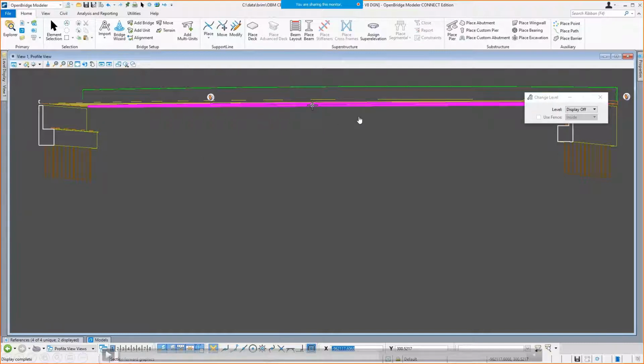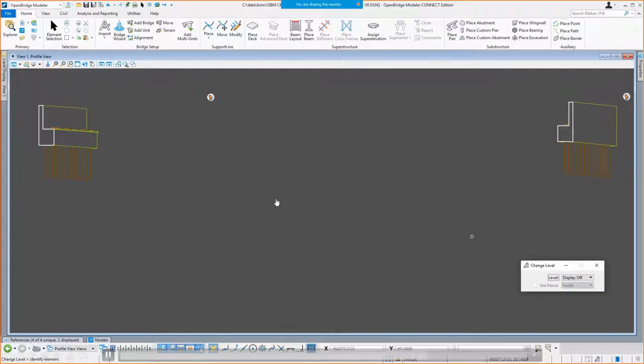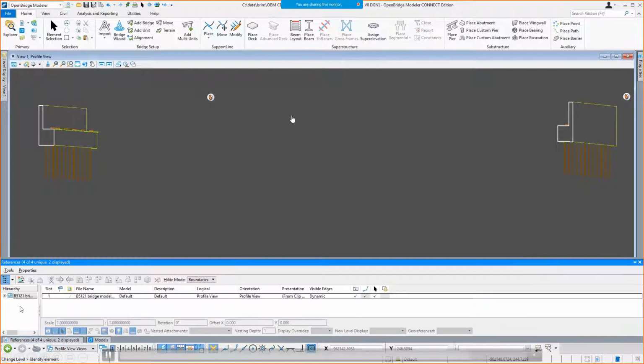Okay, everything else, so apparently the display style I had set for cut said, okay, draw that as a white line. Everything else came in, so everything forward of that came in its original color, symbology, and everything else. So I'm just going to turn off the levels for all those because, again, for this particular drawing, I didn't really want any of the superstructure stuff here.